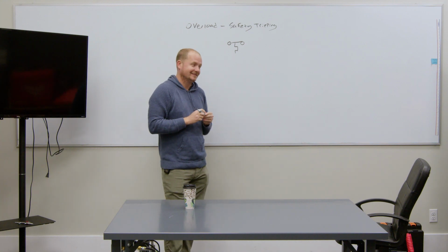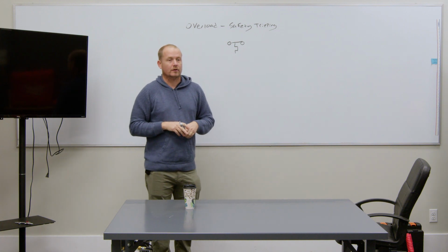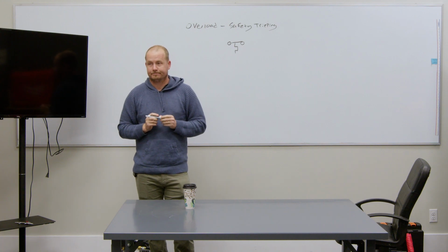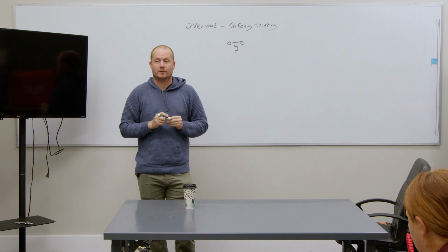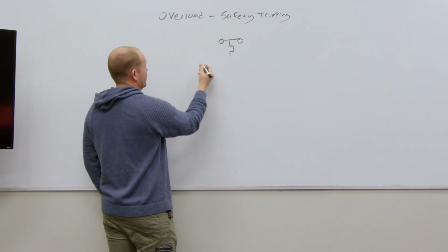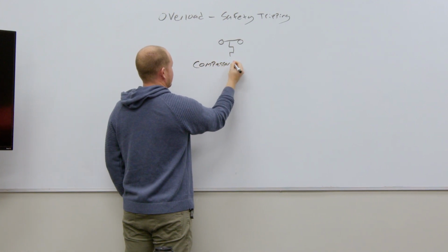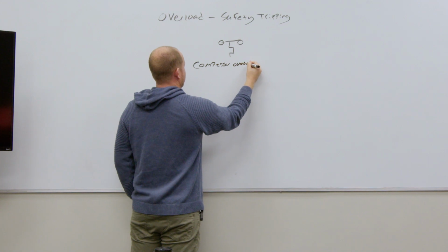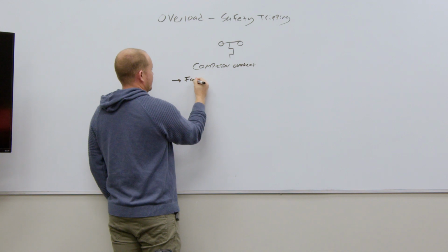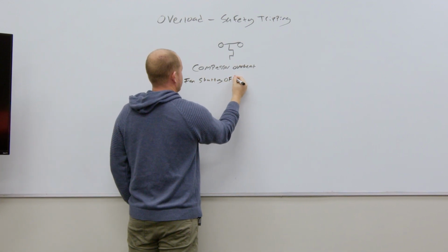Good times. All right, so what causes a thermal overload inside a compressor to open? Overheating. What are some of the reasons? What are some of the things that cause a compressor to overheat? Ooh, okay, we jumped right to it. So we'll just say fan shutting off. Okay, that's a good one. What else?